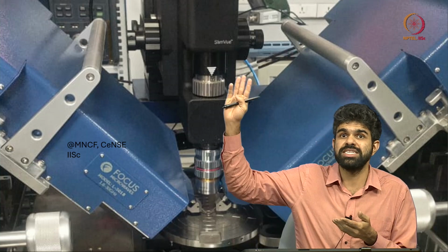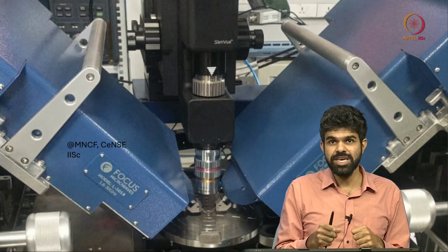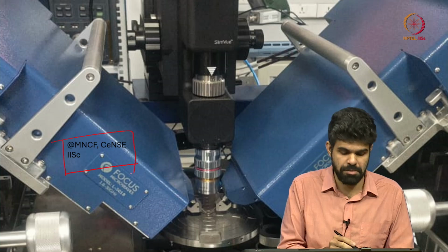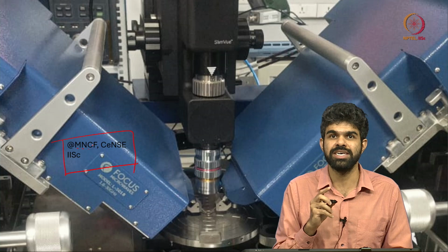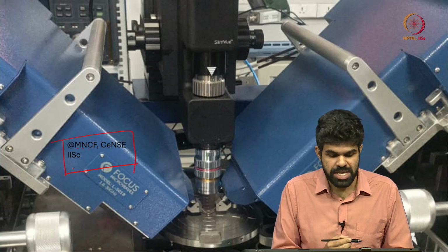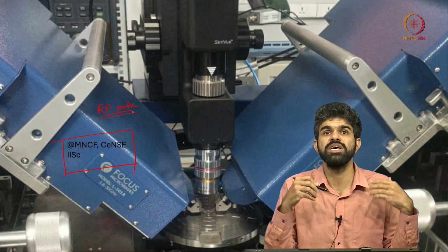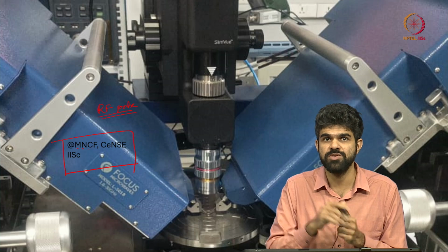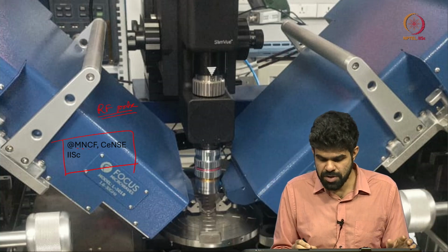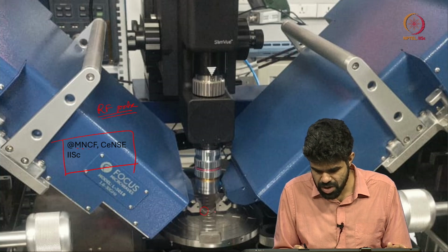All these things exaggerate as you keep going to higher and higher frequencies when you are actually measuring, right. Now here I am showing you one of these probes that we have at the micro nano characterization facility in SENSE. SENSE is the Center for Nanoscience and Engineering in IISc, right. This is an RF probe, used to do RF measurements, which means gigahertz and more than gigahertz. If you have to measure capacitances and resistance, you use these sort of probes. Now, you see that one probe itself, somewhere there is a probe tip, and you are going to connect it to your sample, right.